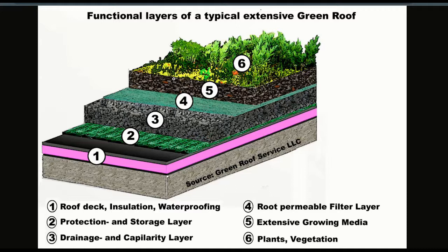We're going to simplify this greatly. We're going to show the roof support system and the rigid foam, which would include that permeable membrane. And then we're going to say this is a foot thick. This layer could be anywhere from probably half a foot to up to a meter thick. And just realize every time you go up an inch in thickness, you're really increasing the weight.